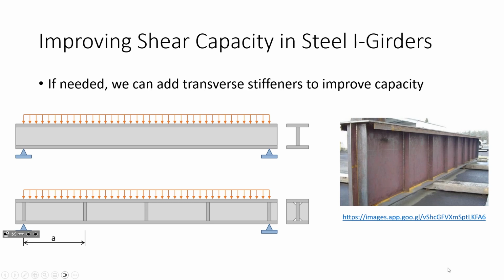Whereas nowadays, it's sort of the opposite. We'll make a girder 5% heavier if we can avoid a lot of welding. So a lot of modern plate girders, when you're driving down the road, will look like this. You might have a stiffener here at the support, but that's about it. Now that doesn't mean we don't use shear stiffeners at all. We do use them, but we only really use them when we can't get around it from an economy standpoint. In other words, if we have elements that are pretty slender and subjected to pretty high shears, then we need to place some stiffeners in there.